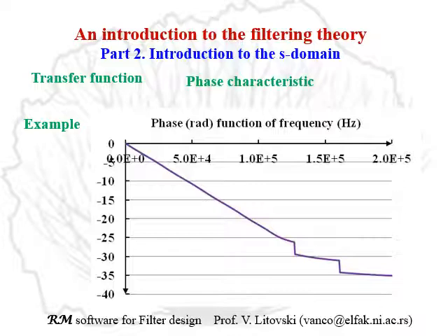One is to note here the jumps in the phase characteristic due to passing the frequency omega through the zero at the imaginary axis, and due to the changing of the orientation of the vector of difference s minus zi. So for low frequencies, it is oriented downwards. For higher frequencies above zi, it is oriented upwards, so it jumps.